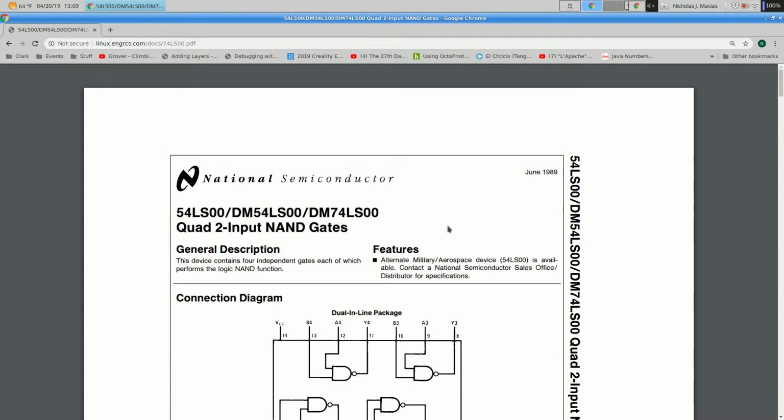So in the 70s, when Texas Instruments came out with their 7400 series chips, and it was the big orange book of part numbers, they introduced 2 lines of chips, 74 and 54. 54 was mil spec. So this was the stuff that the government would buy. It was more expensive, it was higher quality. So mil spec chips could handle more temperature extremes, more vibration.